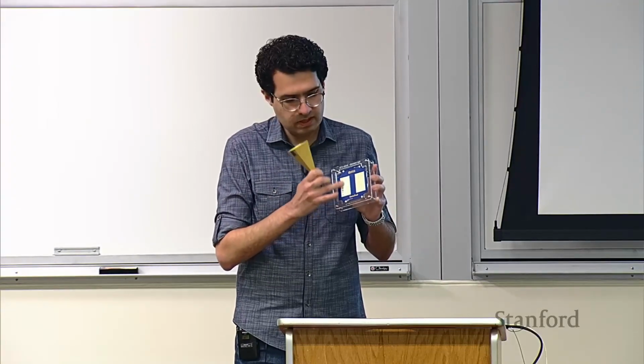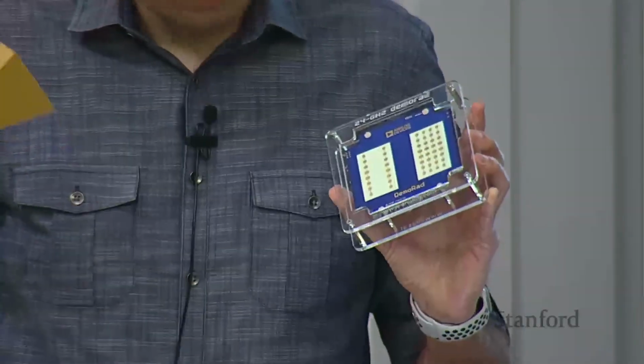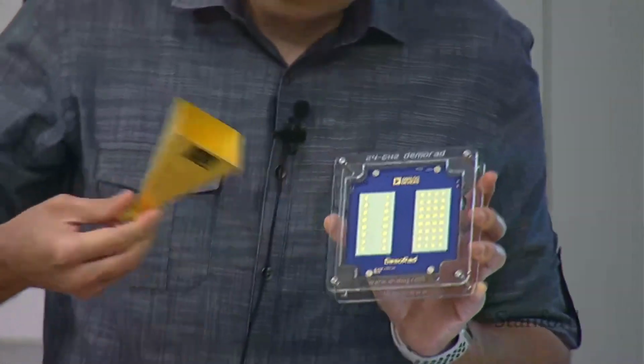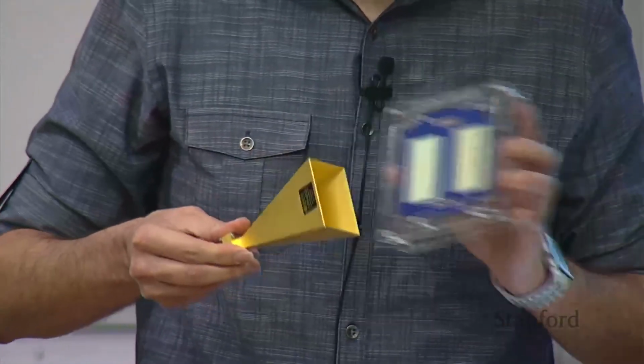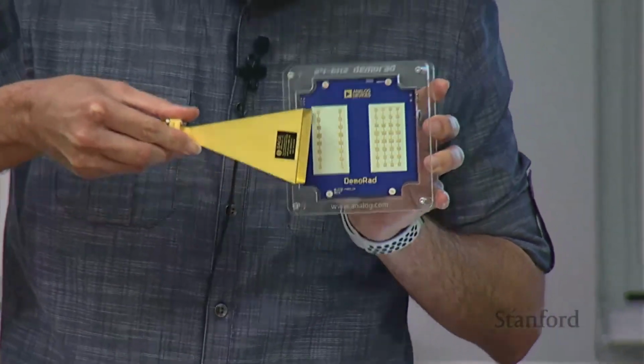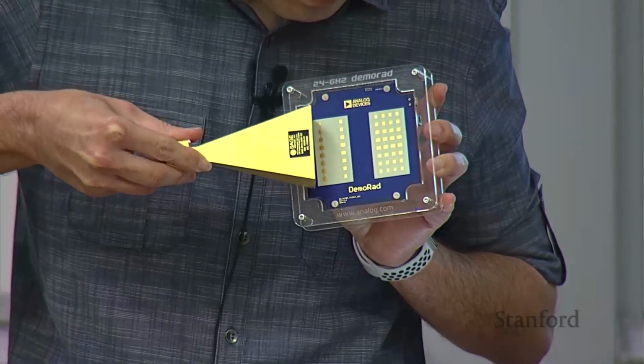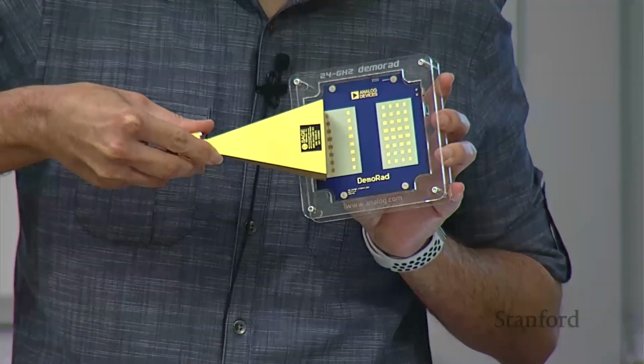It would be almost like, in area, 1/10 of the size of the 24, because antenna dimensions are proportional to wavelength. Now, these two, if I put them next to each other, like the aperture opening of the horn next to this antenna, you would see they're almost the same dimension. Not a perfect match, but they're very close. And that's not a coincidence.